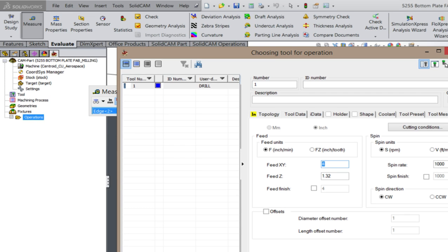All right? So I'm going to put 100 inches a minute. That's pretty fast, right? What about feed in Z? Does that matter? Yes, because we're going to be drilling into the part. So we don't want to go too fast there. And remember, you have kind of a general formula for drilling into materials. You can use that formula as a basis point. In this case, with that small of a drill bit in aluminum, I think I'm going to go something like 5 inches a minute. You might check me with your little formula and see what you get.